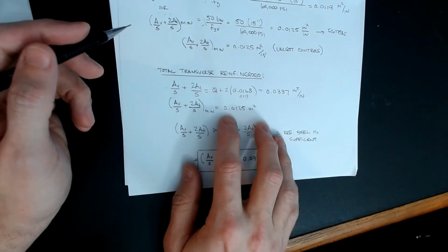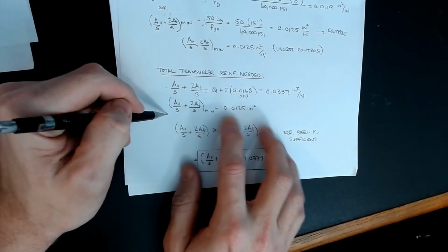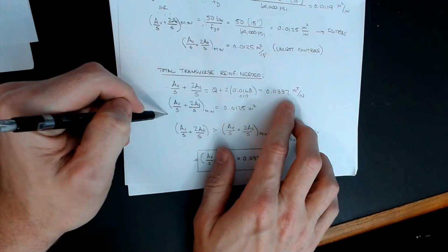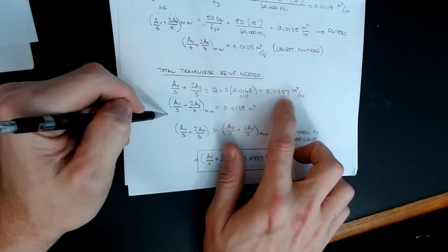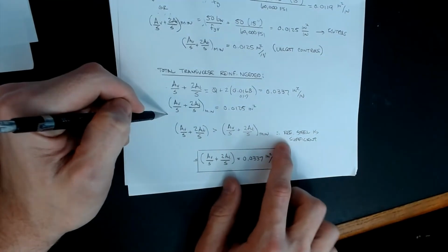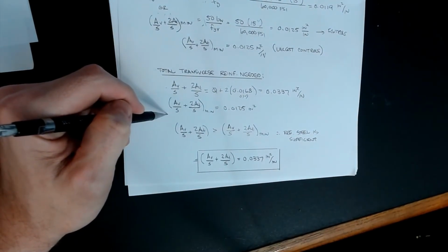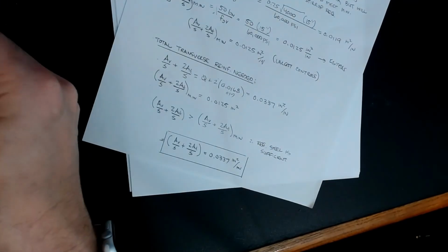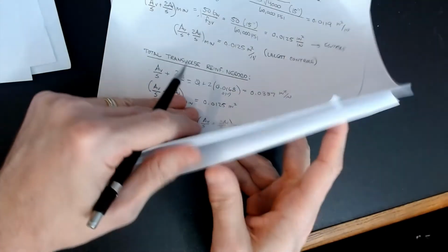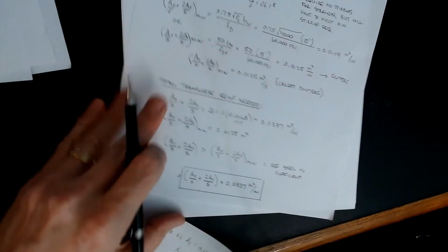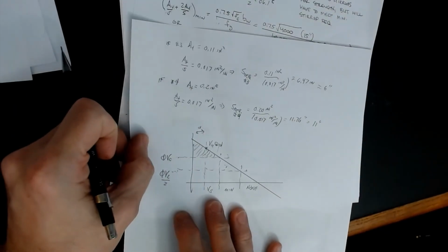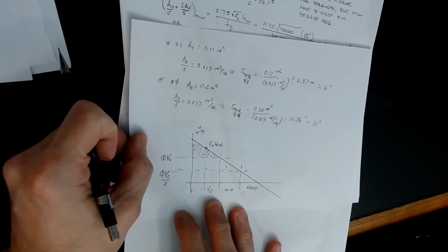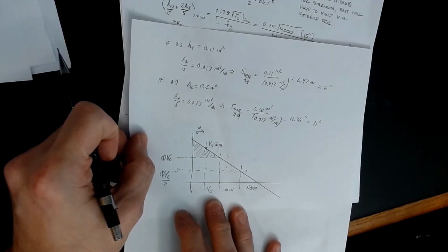And then, if I do the math, my minimum is 0.0125, I gave it 0.0337. So clearly, what I gave it is more than the minimum. We're okay for the steel that we've designed for. You're kind of seeing it? And so that's where we could go then and start playing with, oops, maybe I lost the page. Is it on the bottom? There it is. Now is where you would go in and you would start playing this game. Choosing your sizes, choosing your spacings, and figuring it out from there. Okay? Any questions on that?